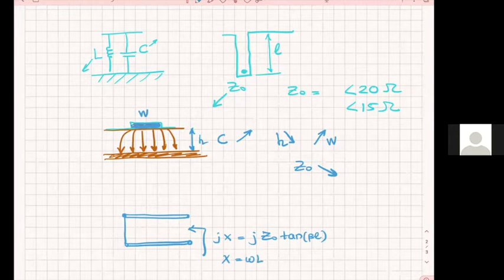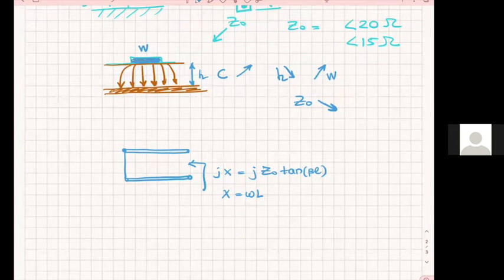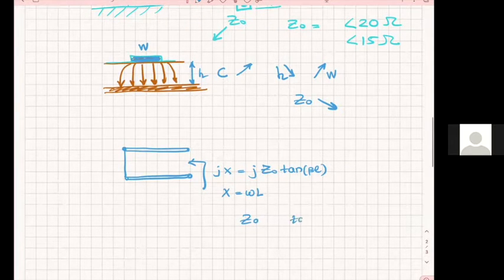If my ωL is a very small number, that implies that my Z0 becomes very small and βL becomes small. What if I want to make Z0 50 ohms? Then I need to make tan(βL) even smaller. Do you agree? So the small L becomes even smaller.